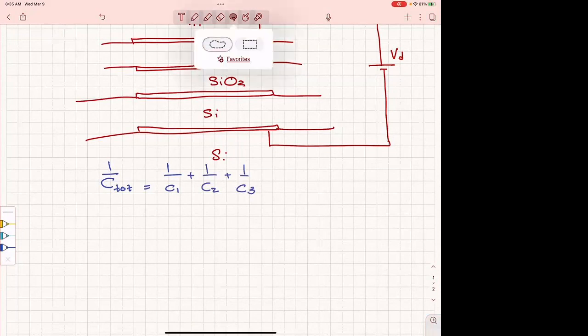Now that is very problematic. Why is that? Because usually when we make capacitors, we want them to have a respectable value of capacitance. And that tells you if for some reason your metal is not exactly facing the other metal through one material of high density that we try to put there, but you have other materials of lower dielectric epsilon R, your capacitance is compromised substantially. Practically, your capacitance will be closer to the smallest of the capacitances. All right, so that is important to remember.